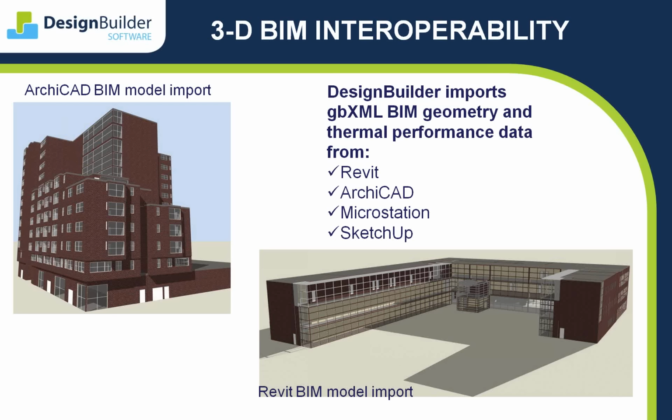DesignBuilder's new GBXML import mechanism enables it to better handle instances where the GBXML file has errors such as missing surfaces, as well as providing automatic story space grouping for easy navigation and edits. DesignBuilder's new tools eliminate gaps between zones, repair non-enclosed spaces, and eliminate gaps in surfaces.